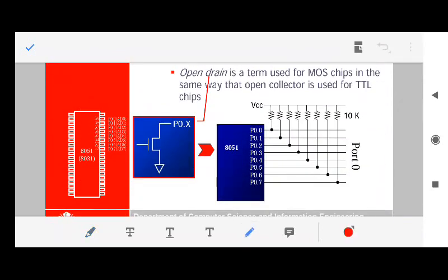One important thing you need to remember is that when you're using the port P0 of 8051, see how to write the different bits of port P0. We all know that port P0 consists of 8 bits. So how to write the 8 bits of port P0? We write them like P0.0, this is the first bit, P0.1, that is the second bit, P0.2 till P0.7. So this is a total of 8 bits. This is how we write the different bits of all the ports.